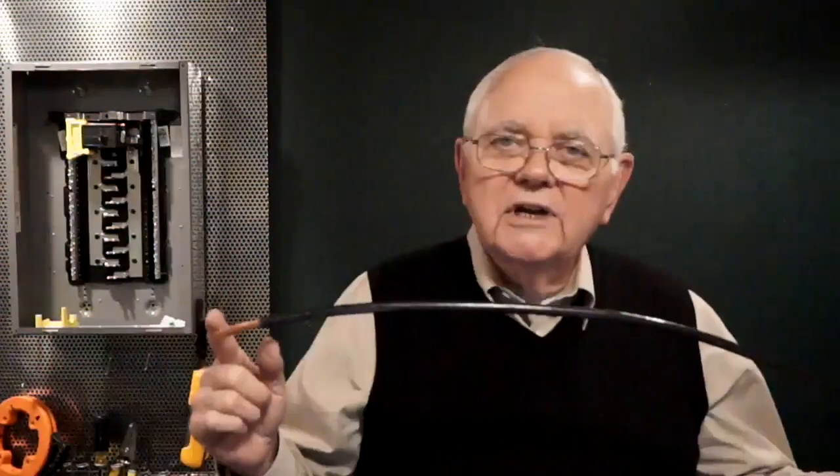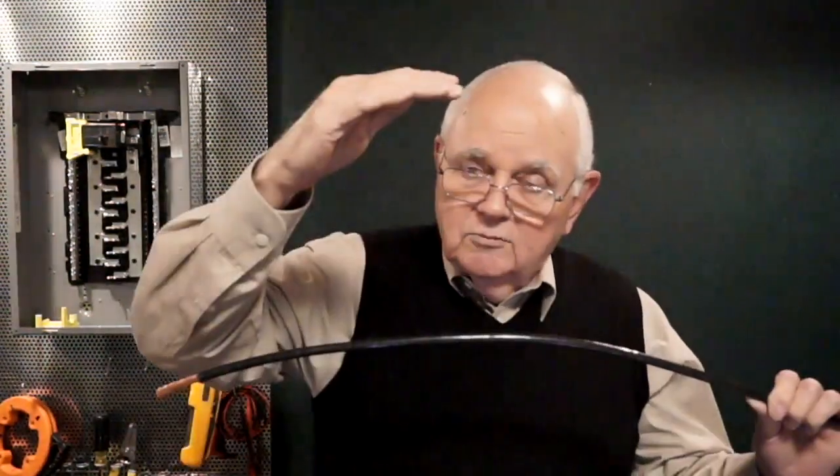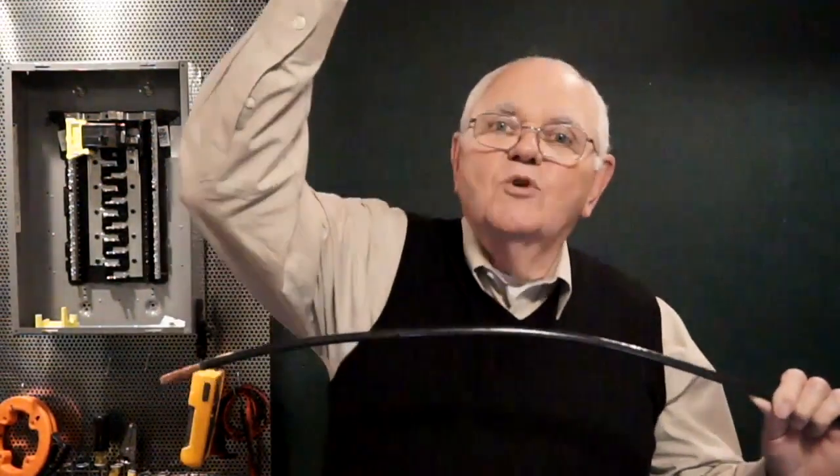As current passes through the conductor, there's resistance. The resistance produces heat. The more current flow I have, the more heat. The more heat, the more resistance. The more resistance, the more heat, and so on.